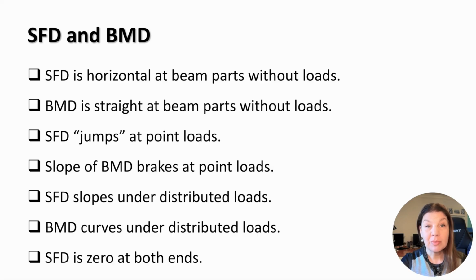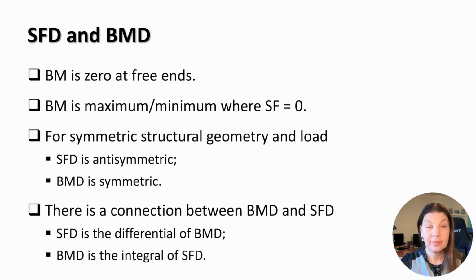The shear force diagram slopes under distributed loads. The bending moment diagram curves under distributed loads. And the shear force diagram is zero at both ends. Additionally, the bending moment is zero at free ends. The bending moment diagram develops extremums where the shear force equals zero.